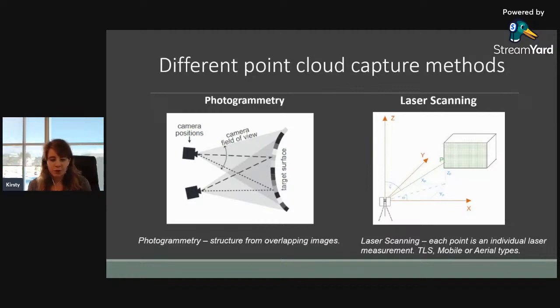A key difference between photogrammetry and laser scanning is that laser scanning is ground captured measurements. The points that are captured are fixed points, whereas photogrammetry is a reconstruction. So the points aren't necessarily fixed, they're calculated from those images. So for this reason, laser scanning is often seen as more accurate. This depends entirely on your project. And for those of you looking at large scale projects, the accuracies can become quite comparable. So it's more of a general rule that laser scanning is more accurate.